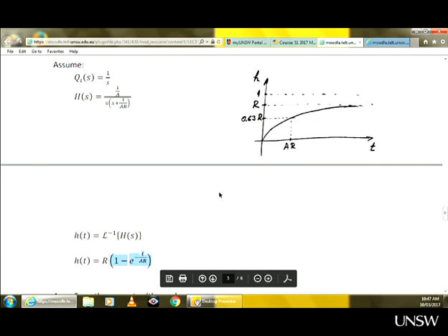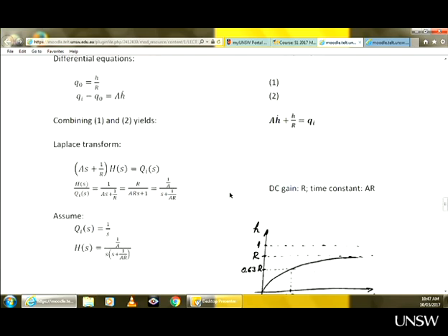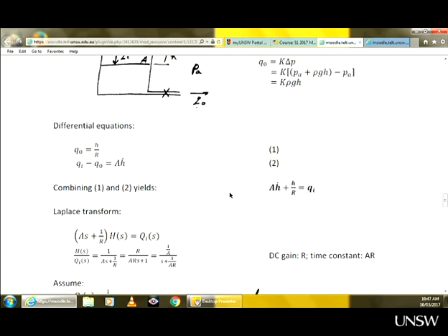Yes? Volume rate. Q, by convention, is cubic meters per second. M dot would be kilograms per second. However, because this is a liquid, we assume there is no compressibility, so the result would be the same if you assumed this was a mass flow. It's different with gases, but with liquids, no difference. It's just an additional rho you're going to have.